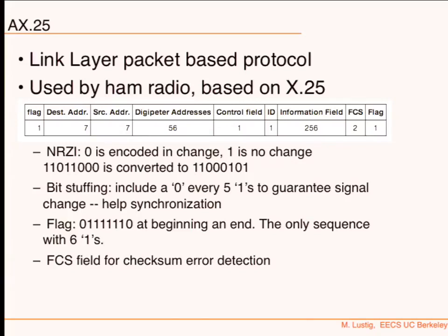Yeah, well, when you generate the filters, generate them on DC, and then complex modulate them to 2200. So when I generate DC, what bandwidth do I use? You need a bandwidth of about 1,000, I think, or 1,200 or something like that. So why couldn't I use 500? Because it's too narrow, so it's not going to capture all the signal. Your signal around that frequency is a little bit wider. It's about 1,200.